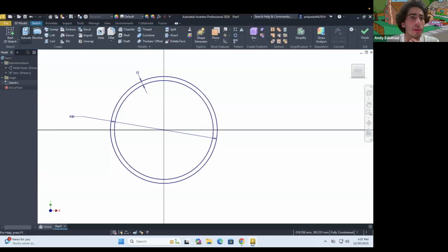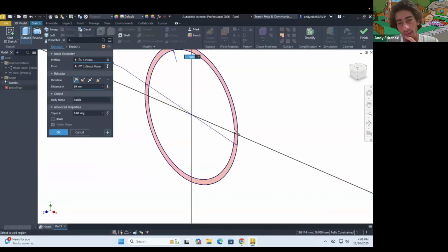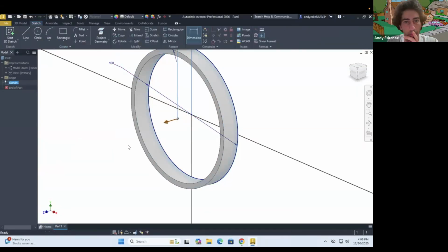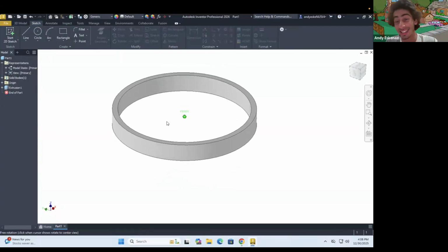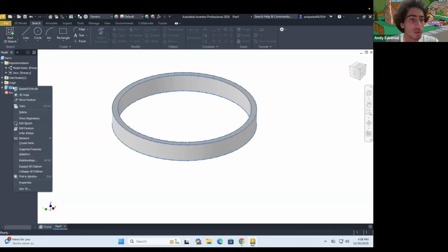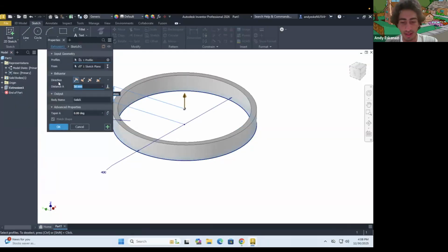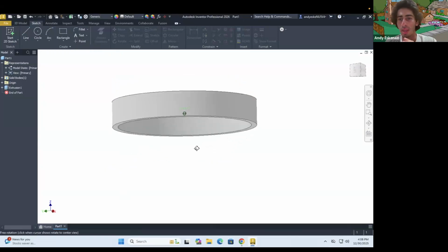And then we'll go here to 3D model, extrude, and I'm gonna extrude this stuff by let's say 50. Okay, that is still too small, so perhaps what I'll do is I'll go here to edit feature and I'll make that really 70. I think that's better. Okay, good.